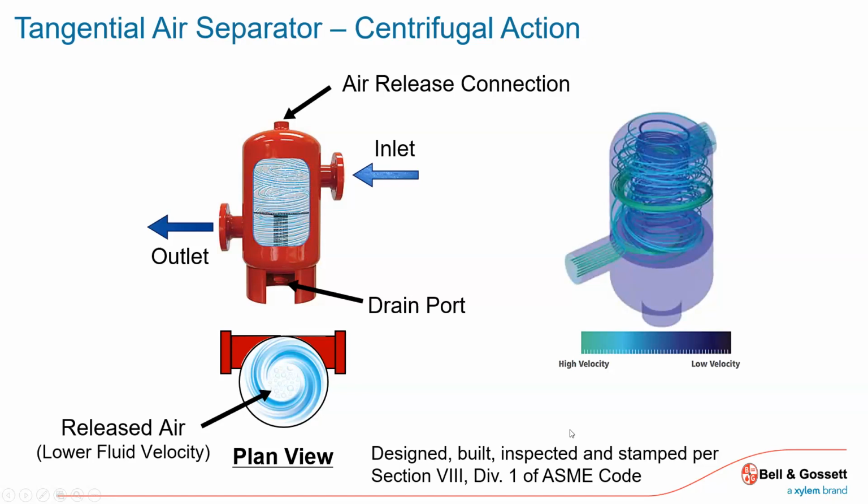And the lighter air gathers in the middle, where there's like this stainless steel collector tube. And it's low velocity, and it will collect and just get released through a high capacity vent. It's very effective, been around a long time, but it does a really good job. And that's, again, another very common device that you will see and probably specify in the commercial space.